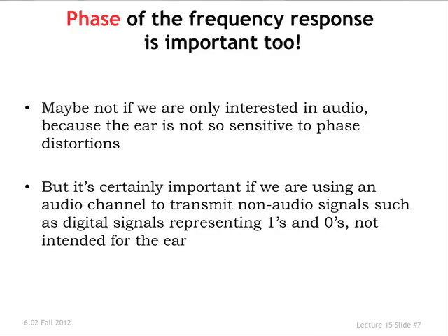Okay, but the phase of the characteristic is important too. It's not important maybe when you're talking about sending audio on a speaker, but in AudioComm in the lab, you're actually sending pulses across it. You're communicating something other than audio. You're actually trying to get a signal whose particular shape matters. It's not how you hear it, but what it looks like before you sample it. Okay, so in settings like that, the phase characteristic is important as well.